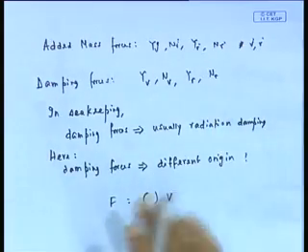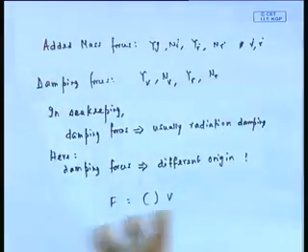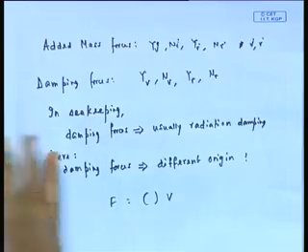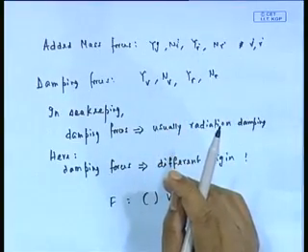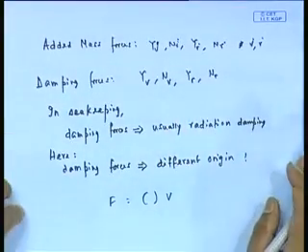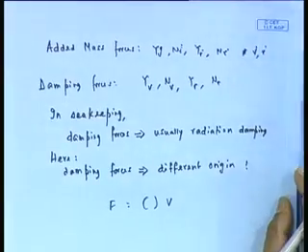Any force in proportion to velocity is called damping force, and any force in proportion to displacement you call stiffness or static force. So, here because of the nature we are calling it damping force, but this damping force should not be confused with the seakeeping damping force that we have done in the first part of the course. Because the added mass force remains same, but the damping force does not remain same, that one must recognize. This we can keep going on, but let me now go to one interesting point.